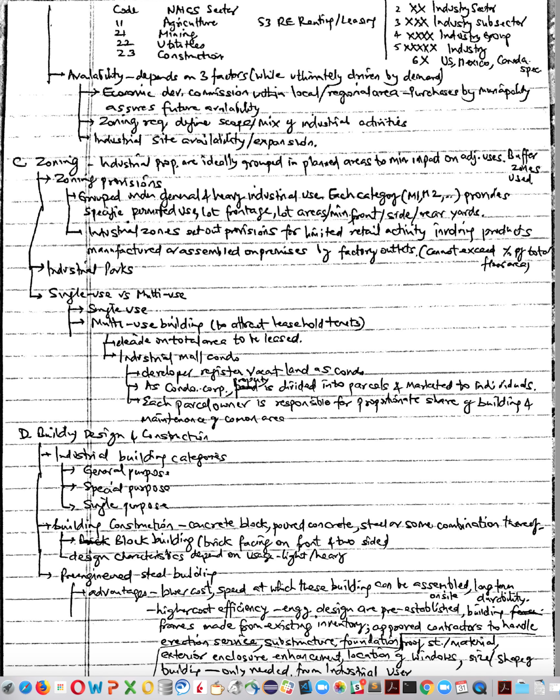Regulations impacting industrial parks include compliance with performance standards relating to noise, vibration, odors, toxic and noxious materials, radiation hazards, fire and explosive hazards, glare, and heat. An industrial park may serve as a buffer between heavy industrial activities and a business or residential district. An industrial park requires comprehensive planning to ensure adequate roads, proper land use, site coverage, lot sizes, and minimum acceptable architectural and landscaping requirements are met.